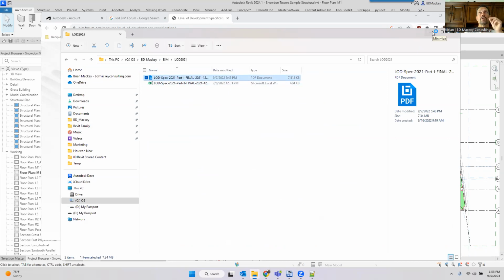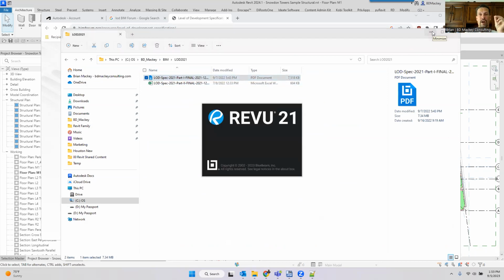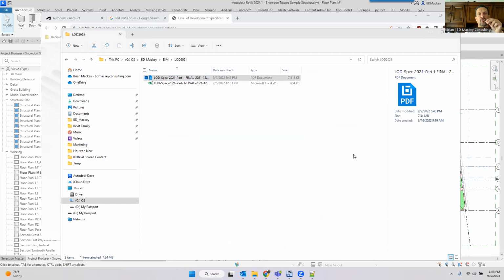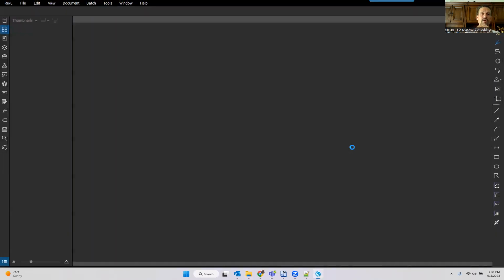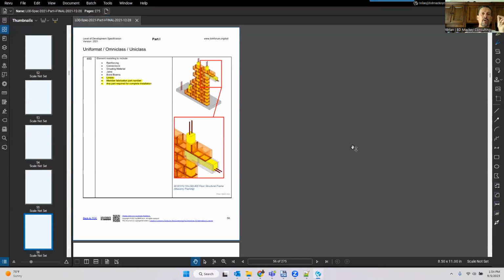If you talk to most end users, and I've worked with several airports, they say we need LOD 400 or 450. And I sit down, I show them what that means. What they truly want is LOI 400. The LOD can be 200. And what I mean by LOI is level of information. Most places out there, they don't need the fabric mesh modeled, the screws modeled on the chair you're delivering to them. It's a flipping chair. They need a dumb 2D symbol for the chair. They need the level of information.